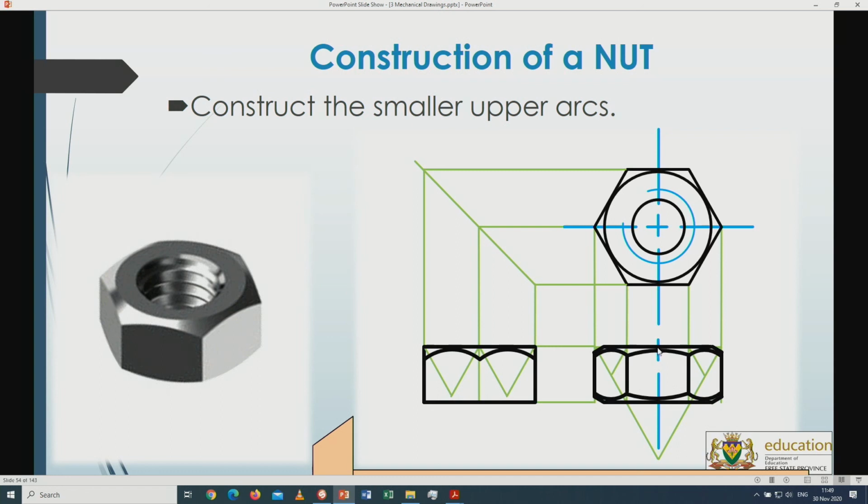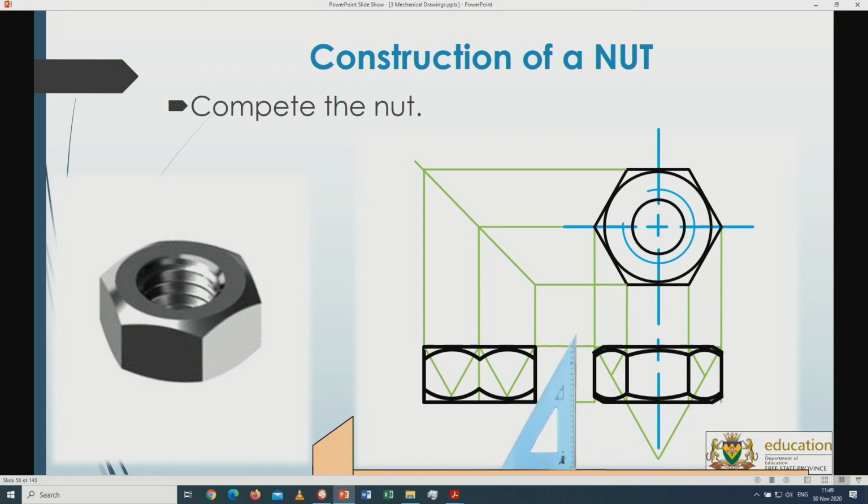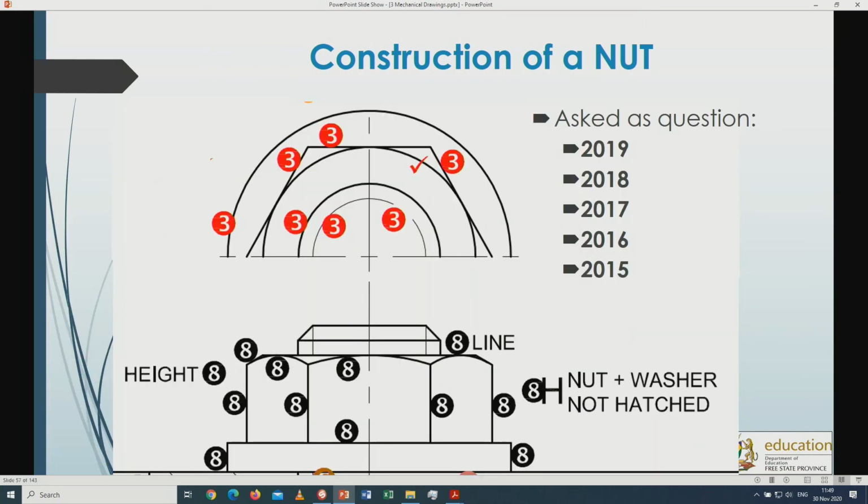Now, very important, ladies and gentlemen, if you do make use of a circle stencil or a nuts and bolts stencil, remember that that must be a tangent arc towards the line itself, tangentially touching that area. There mustn't be a gap on those points at all. And then of course the bottom part of this part is exactly the same, and that's basically the left view without the final line that I have to draw in at that point. So that's the construction of a nut itself.